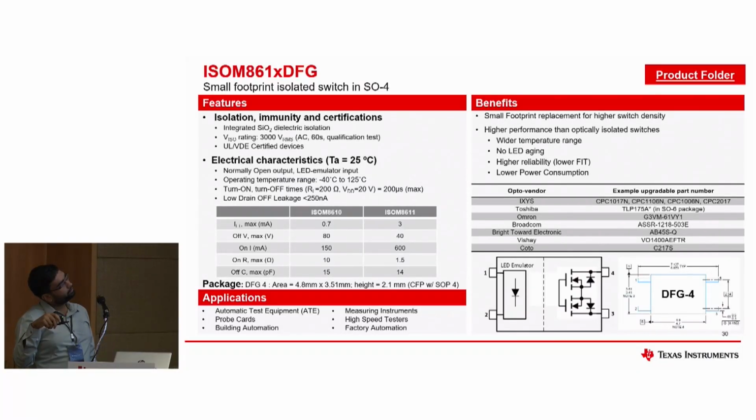some of the main specs to look for in these devices are the switching, the leakage parasitic, the current leakage, and your bandwidth. How fast of a signal you can transfer from pin 4 to pin 3. So in all of these, this device performs on par with the competitors.